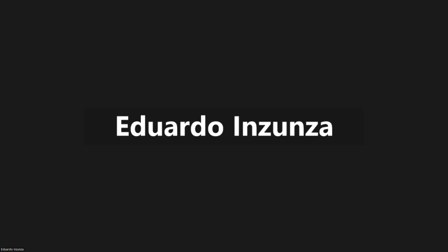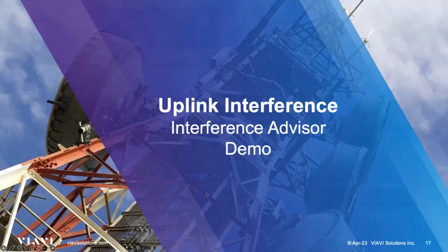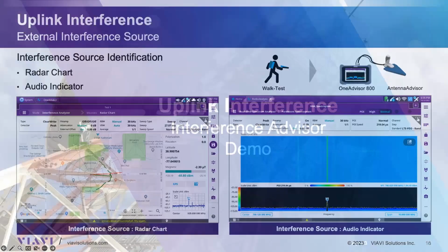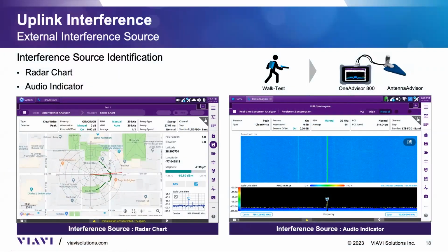Okay, so let me just go back to the presentation. So next, we have found the location now. Now that we have found the location, it is a matter of finding the source. So what is that device that is generating that interference? For that, we then need to do a little bit of a walk test with a directional antenna. And typically we just look for that type of interference.